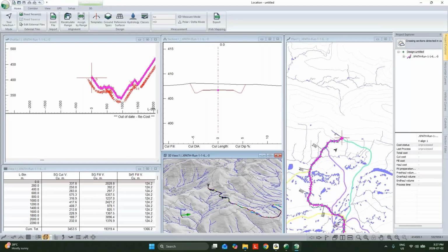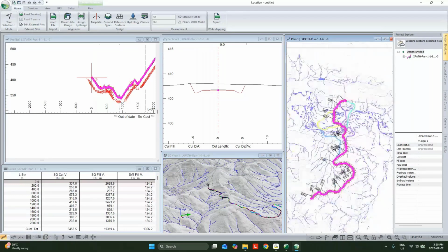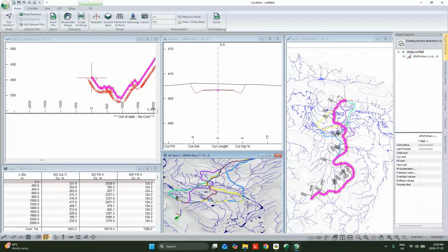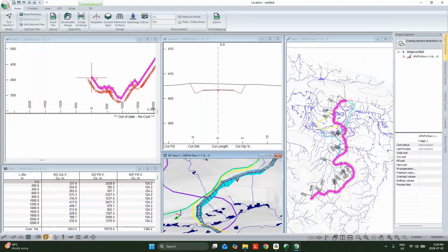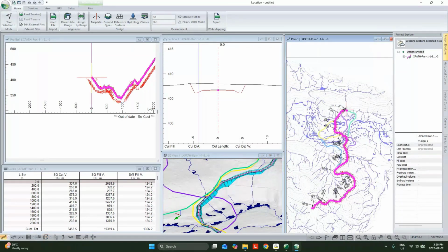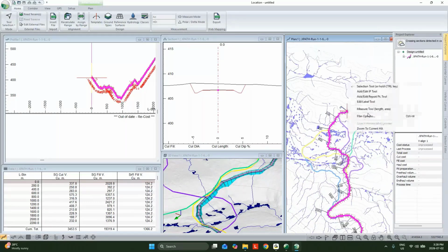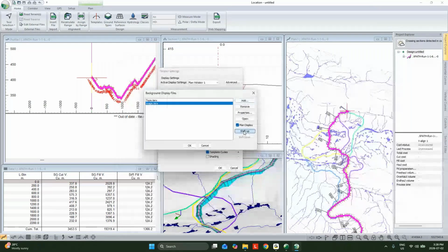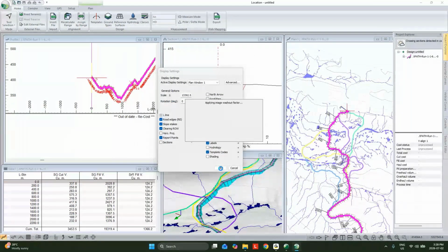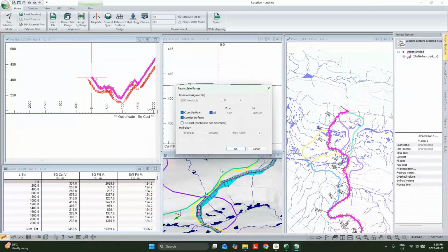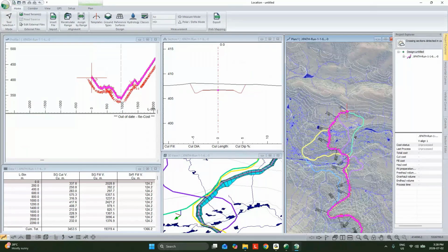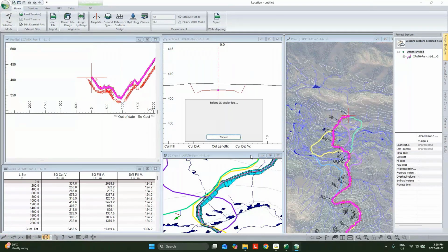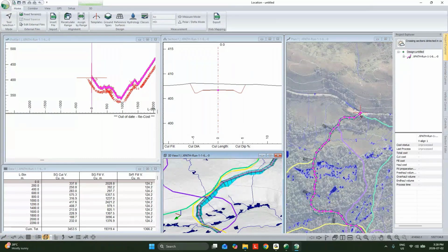With this guy here, we can pan around. We can familiarize ourselves with what we're looking at. Now, we can see that the road that we're designing right now has an actual cross section associated with it, a 3D surface being calculated. Now, we had that ortho. If we want to add the ortho, it was a different terrain file. We're going to add that into this guy here. So there's our background image. And we could note that this Path Explorer solution that we've got is a really smart line on the map, but it's a polyline.